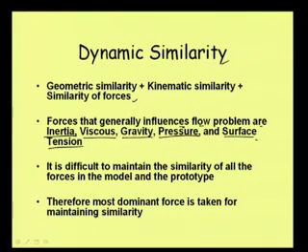Now, there are different forces and it is difficult to maintain the similarity of all the forces in model and prototype. Practically, if we try to maintain similarity of all the forces in model and prototype, that becomes almost impossible. And that way, maintaining dynamic similarity in the true sense, we cannot have. But still, we always try to maintain dynamic similarity by maintaining similarity of that particular force which is dominating that particular flow phenomenon or flow problem.